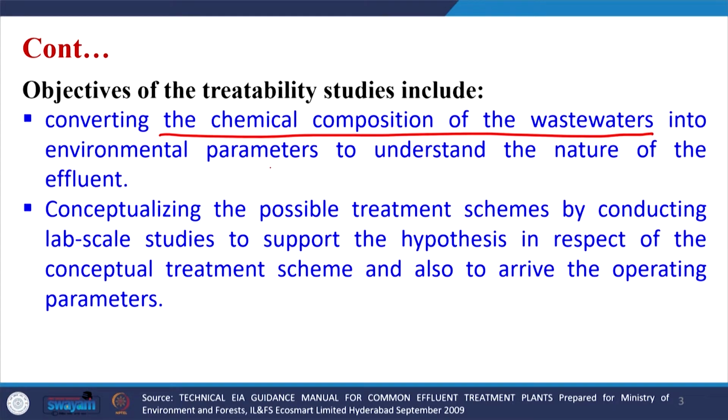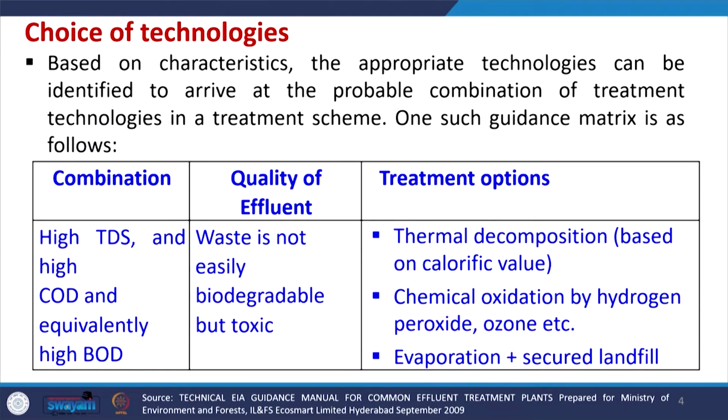We can understand the nature of the effluent being generated and how we will treat the water, and it also helps in conceptualizing the possible treatment schemes beforehand by conducting lab scale studies. So the treatability studies are very important in finding out the chemical composition and the possible treatment schemes. Now, what are the different choices of technologies?